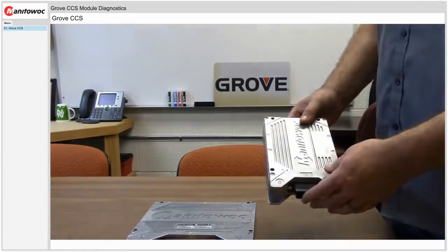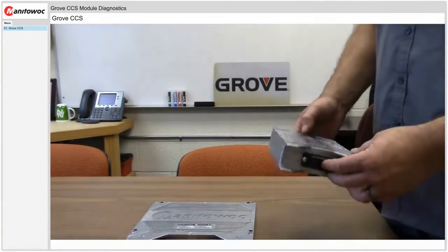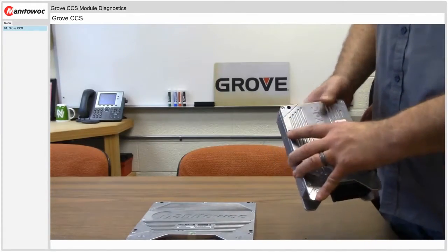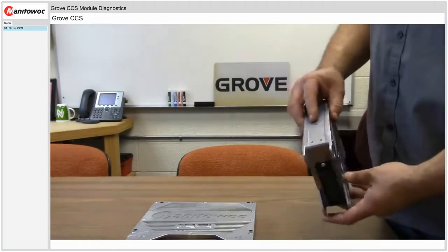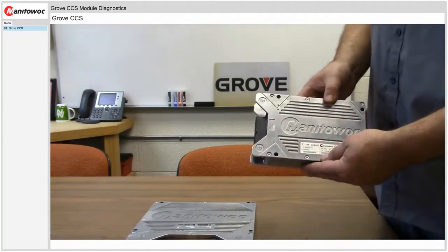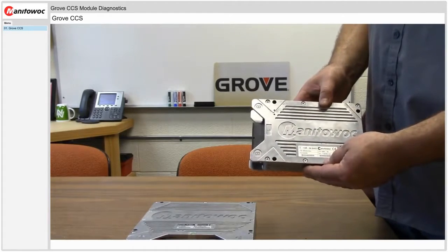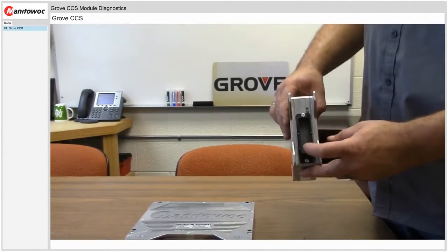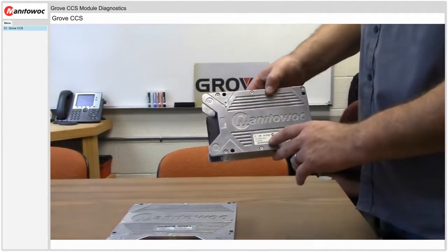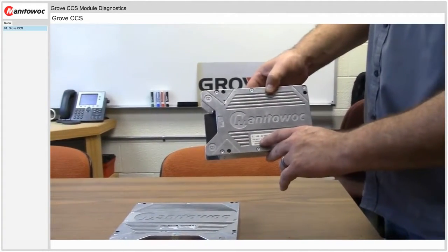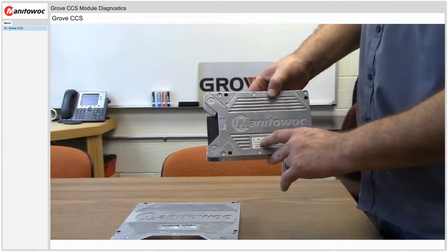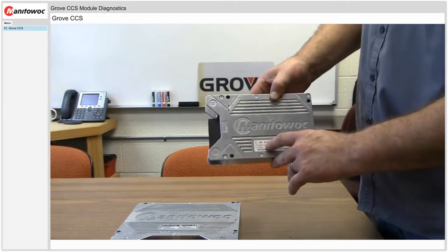So to start with, we'll have four different types of modules used on CCS era machines. Two smaller type modules that have the exact same cases on them will be the SCMs and the IOSs. Physically, the difference between an IOS and an SCM is only the amount of pins located in the plug. For technicians' reference, there is an identification tag located on every individual box that tells them if they're dealing with an SCM type module or an IOS.